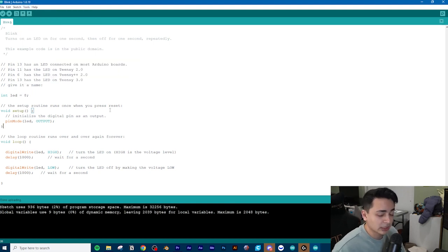If it's still not working, you can unplug the USB cable from the Arduino side and plug it back in. There's also a red button on your board that's a reset button. I'll do that and unplug it and plug it back in a couple times. If it's still not working, I'll restart my computer, but some combination of all of those will usually fix the issue.